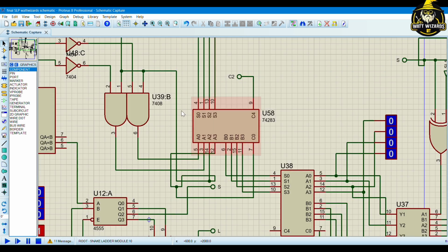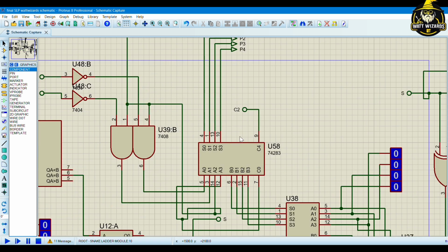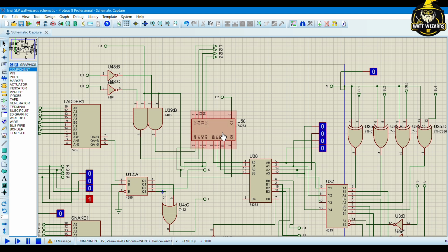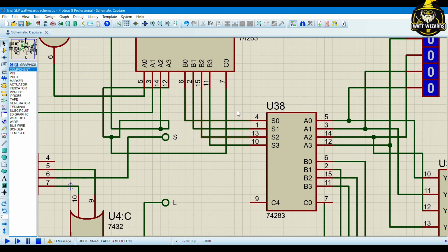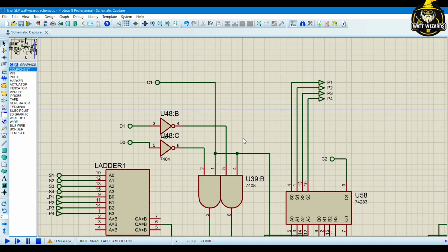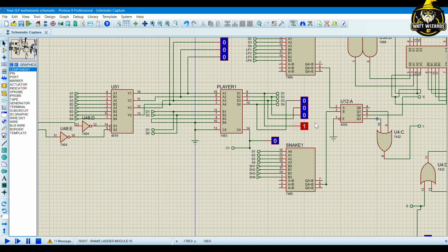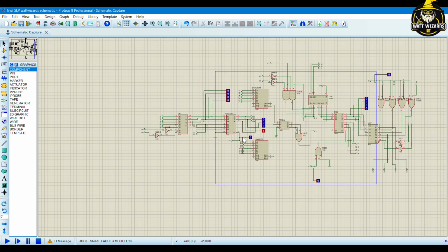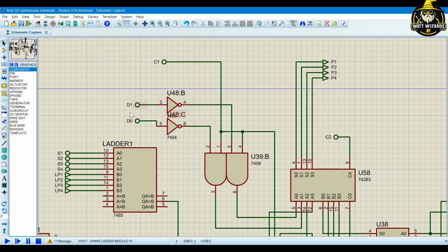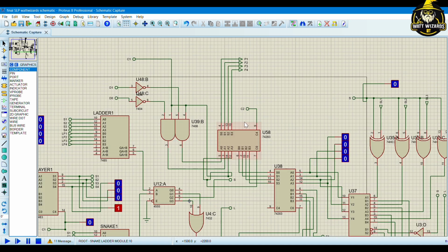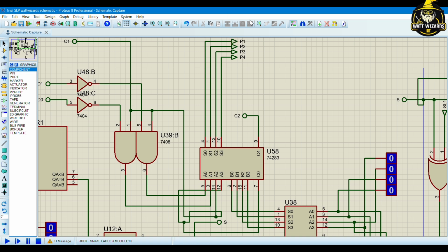But we used this extra adder to solve the overflow issue of our board. If our player is in 15 or 14 position, then this adder will work. Normally, the real value of the summation will pass through, and this configuration over here won't work as the C1 terminal won't get any signal. But once the carry out will be here, the overflow will start happening, then the C1 terminal will get on, and it will let the inverted dice value pass through this adder, and also this adder will start working as a subtractor, and it will hold the new player position in the board.